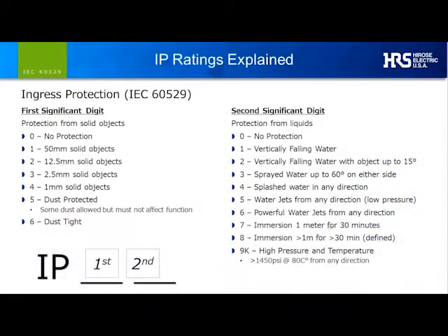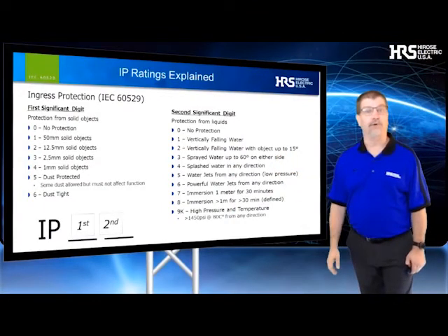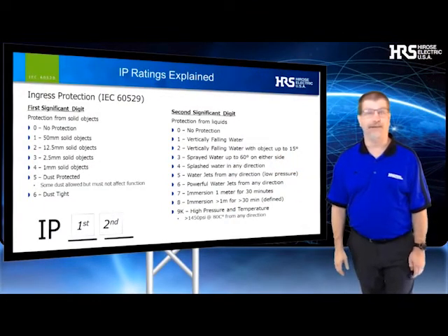Here we can see an example of the different IP ratings, all in a big chart here. When folks say that they're looking for an outdoor connector, they are typically referring down the bottom here to IP67 or IP68 requirement. But don't discount the other options. Just because a connector or device is rated to IP67 does not mean it passes IP66 water jet testing. Since IP ratings are an extensive conversation, we're just going to leave it at this chart for your reference right now. If you have more questions, talk to us about your application, and we will work with you to find the best connector option.